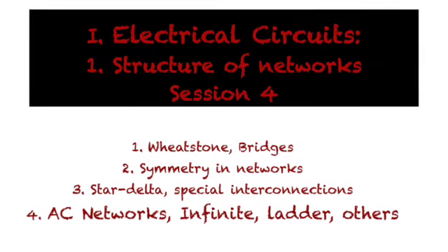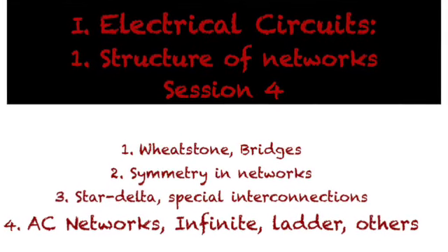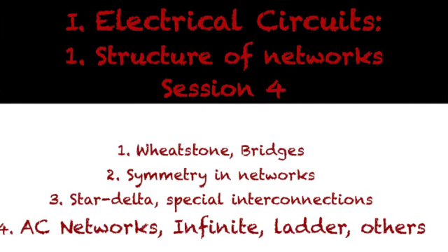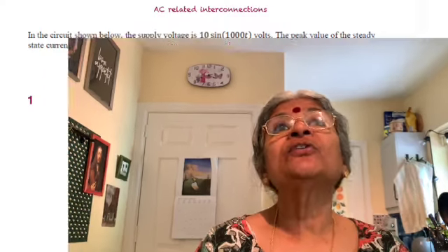Please remember that the concepts will be discussed along with the problems, because the concepts with respect to AC are a little different when compared to the concepts associated with DC. Methodologies too. If it's an AC circuit, what I recommend is always to have a look at the source in two aspects. One, of course, is the magnitude, which either is an RMS value or is a maximum value. Here, what is given is a maximum value because it is succeeded by the sinusoidal content. Next point is to look at what is coming with t.